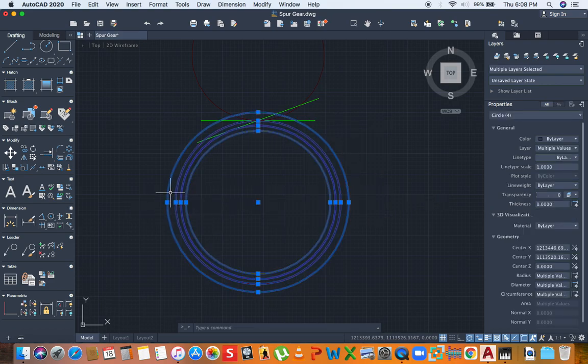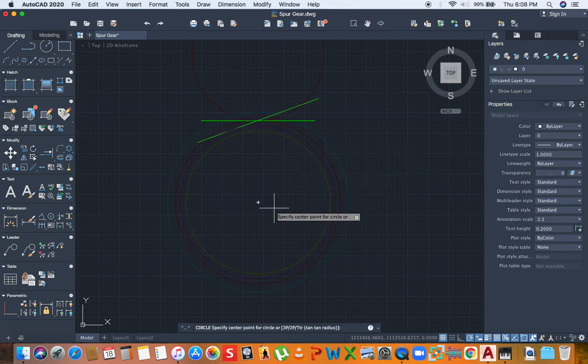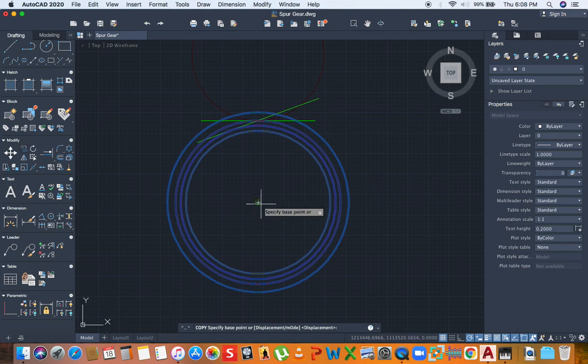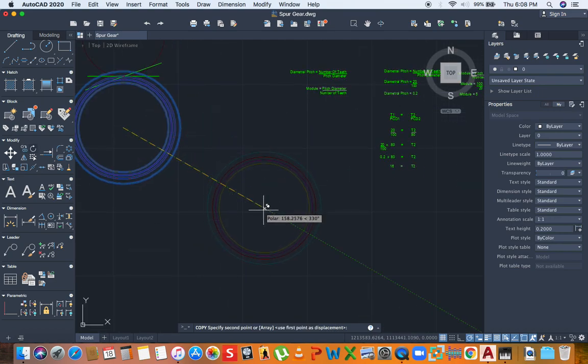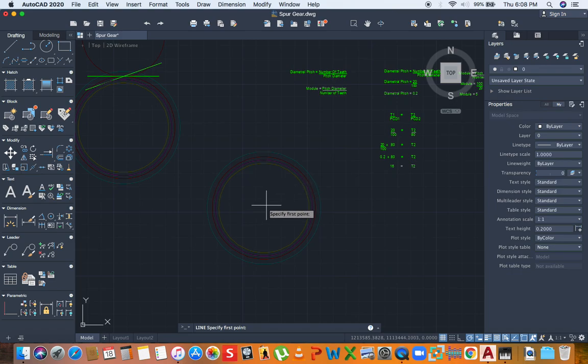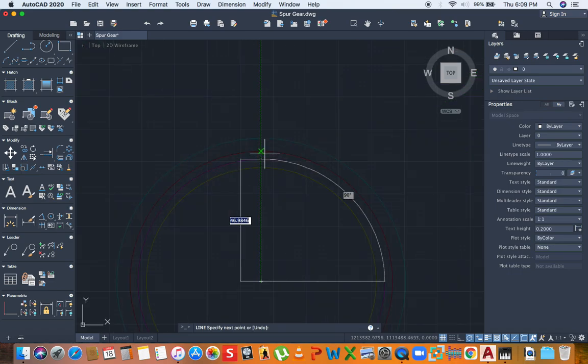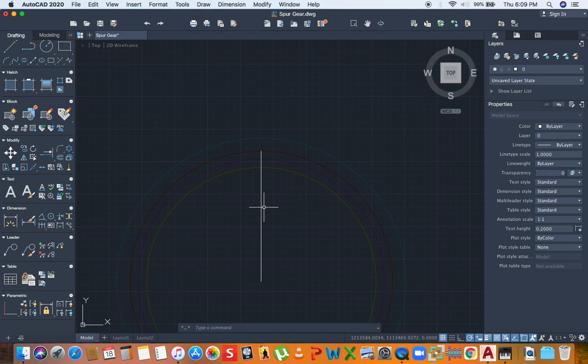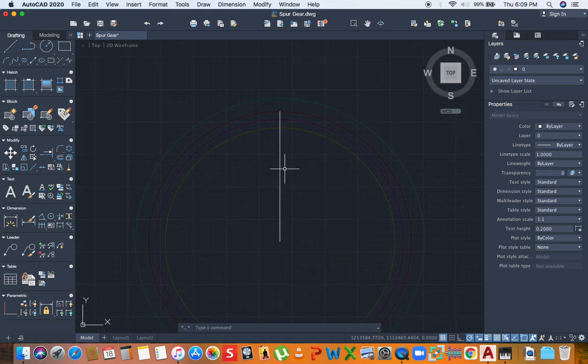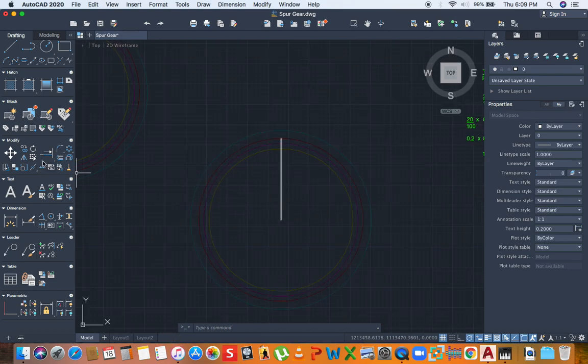construct our involute curve. Now I'm going to copy this. Take it out of the way. I'm going to bring it here. And I'm going to divide it in some spaces that are equivalent to the number of teeth. Now there are 20 teeth, so I'm going to divide it in 20. I'm going to use a command that is called array. It is right here. Now you have different types of arrays. You have rectangular array, path array, and polar array. Now since we are operating from the center of the circle, we'll use polar array.